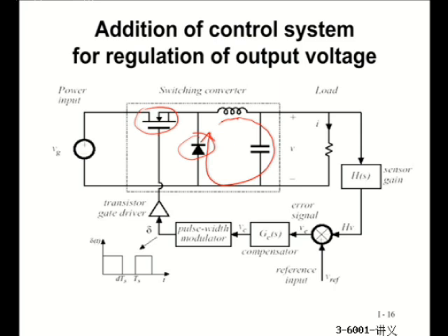Okay, and this is going to be very high efficiency. You can see inductor and capacitor, they're not consuming any energy. Diode under switching mode, IGBT or power MOSFET under switching mode also consumes very small energy. So the efficiency ideally is going to be approaching 100%. So this is the solution, the power electronics solution we're looking at.